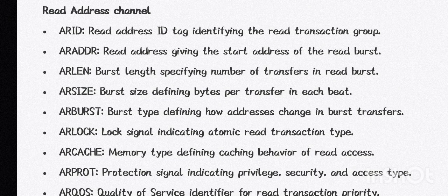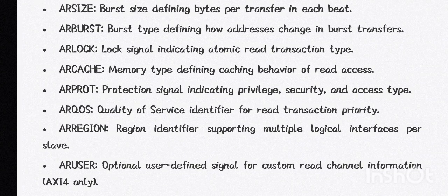ARVALID indicates valid read address and control information from the master. ARREADY indicates the slave is ready to accept read address and control signals.